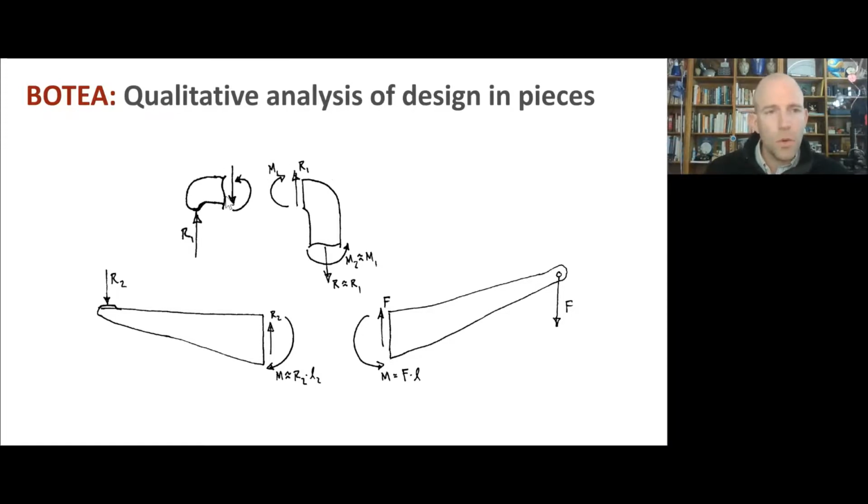So I want this thing to be kind of tall on this face. Now this part, my moment's going to get a little bit bigger because of this offset, but it's close to being a constant moment through this part. So it wants to be tall and consistently so.